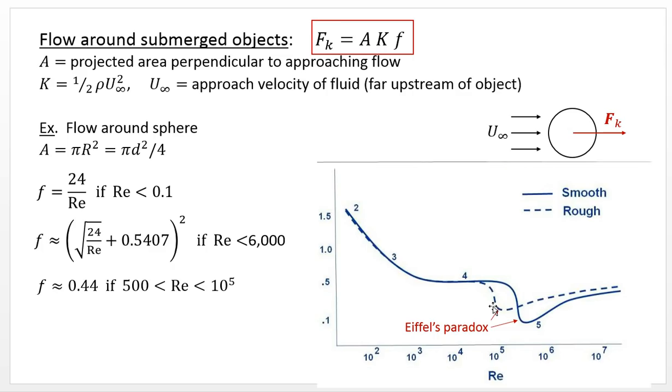And so what this means is, if one's hitting a golf ball, a lot of people can't hit the golf ball at a high enough velocity to attain this Reynolds number for a smooth sphere. However, they can hit it in this range of Reynolds numbers, and therefore when the golf ball is rough, the drag is going to be much lower than it would be if the golf ball were smooth, and the golf ball is going to go a lot further. So you get increased range on your drives or other strokes by using a rough golf ball versus smooth. There are other reasons for the roughness as well, but this is a simple fluid dynamical reason for it.